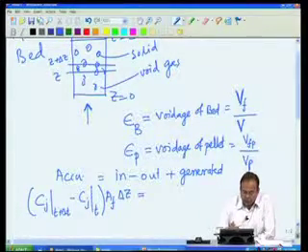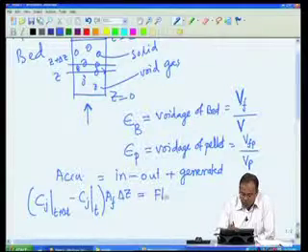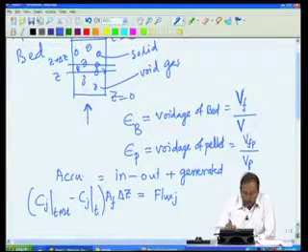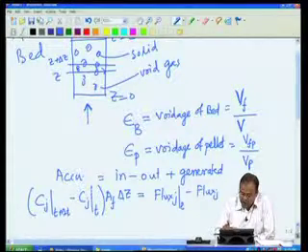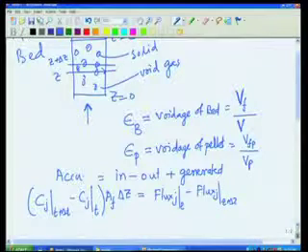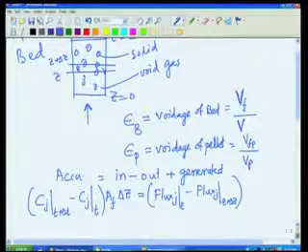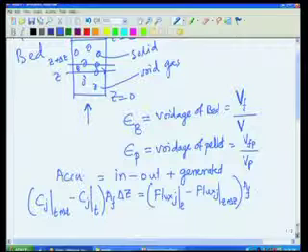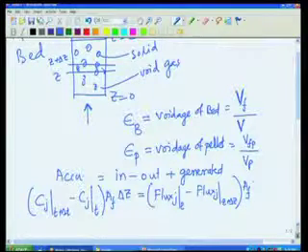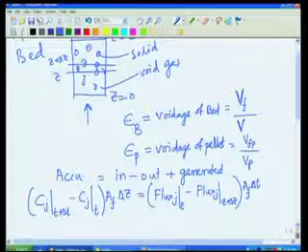Now, this accumulation is the result of flux of J that is coming in at Z minus flux of J at Z plus delta Z in time delta t, and flux is again in void volume per unit void area. So, that is AF into flux in time delta t. This is what the moles of J would come in and go out. And what about generation?